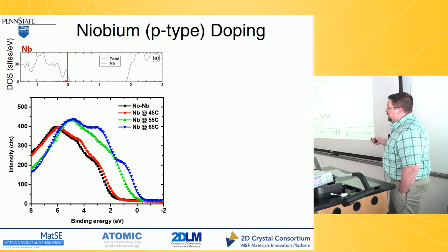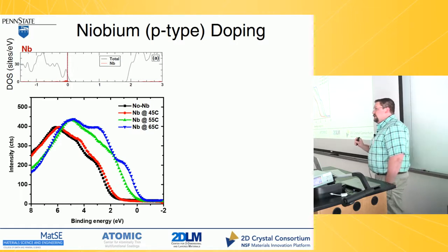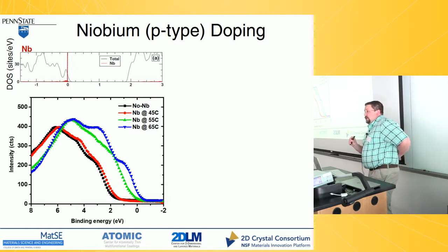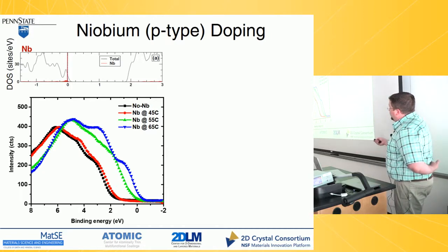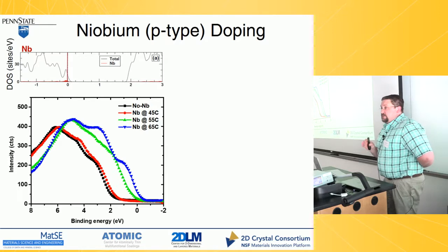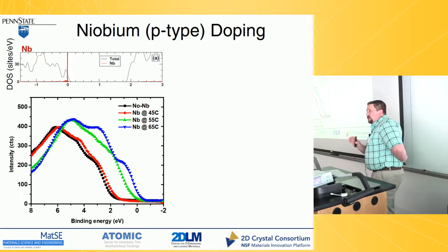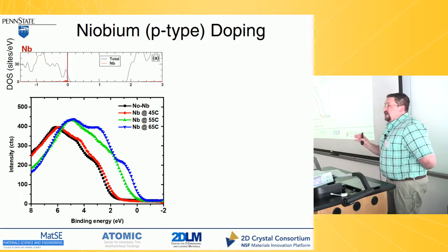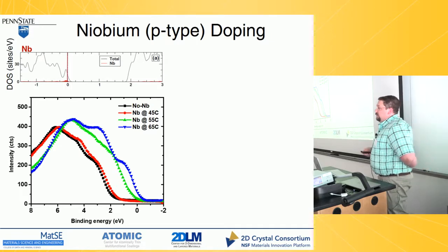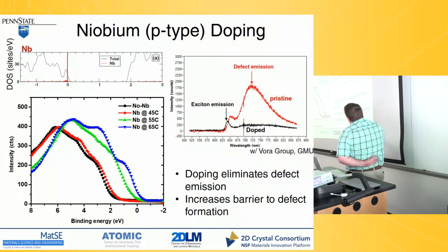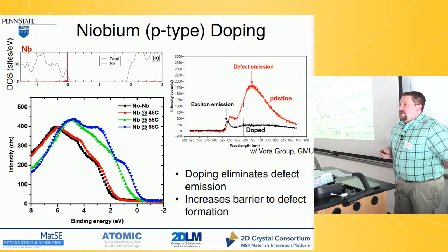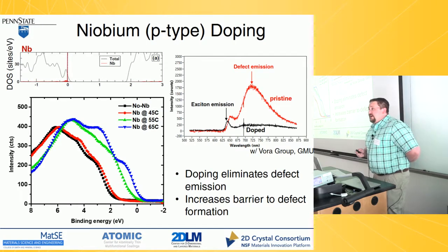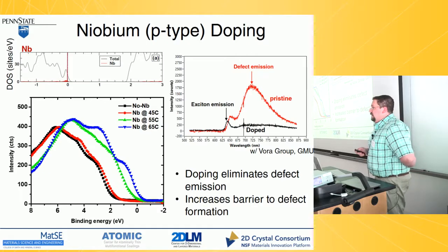So this tells us that we can very clearly introduce niobium into the system, substitutionally dope it into the material, and then be able to induce this to be degenerately p-type. So now you can start tuning MoS2 n-type to p-type on monolayer materials, not in bulk growth crystals. So it also dramatically reduces the low temperature optical defects that you quite often see in MoS2.